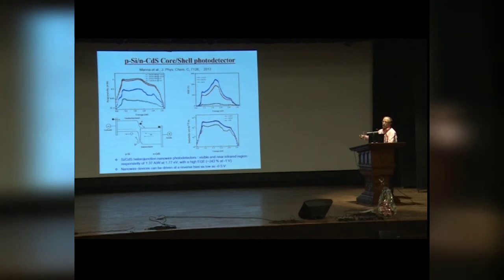Okay, and we see that silicon is a near infrared band edge. On the other hand, cadmium sulfide is in the visible region, and you get a very nice broadband response of this detector, which works from about 0.8 electron volt to 2.8 electron volt. So first, it is a very broadband detector. Now, what about the responsivity? That means how many carriers were generated per incident photon.